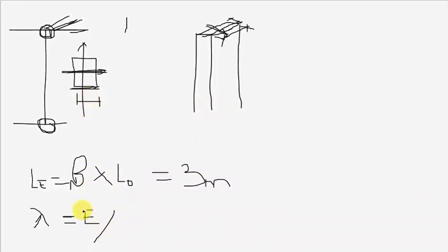So you take the effective length, which is LE, and divide that by the dimension responsible for bending. Let me call this dimension D. If our effective length is 3 meters, that is 3000 millimeters, you divide that by the dimension responsible for bending.